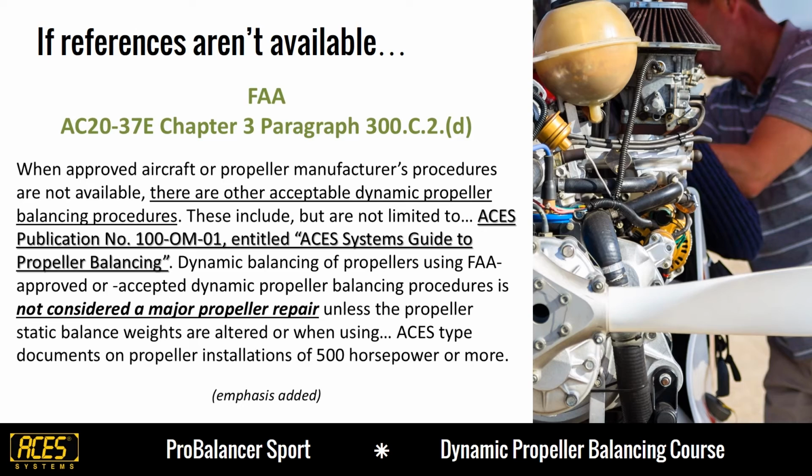According to Advisory Circular 20-37E, this procedure is not considered to be a major propeller repair unless the propeller static balance weights are altered or when your engine has more than 500 horsepower.